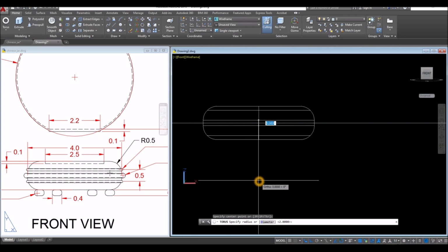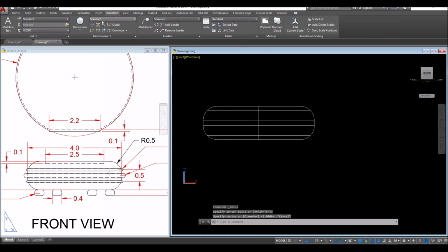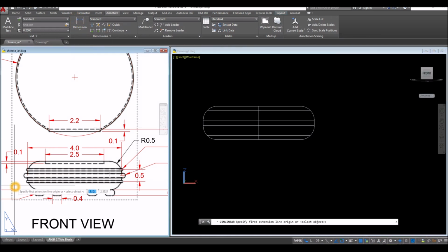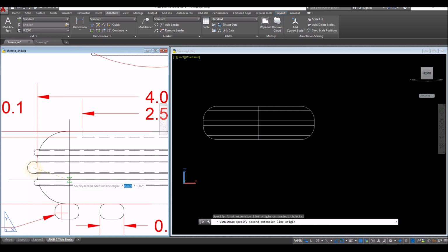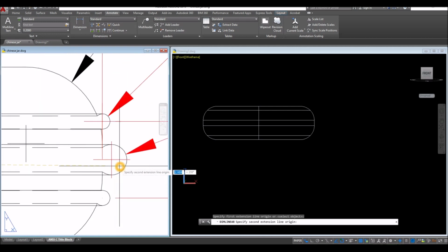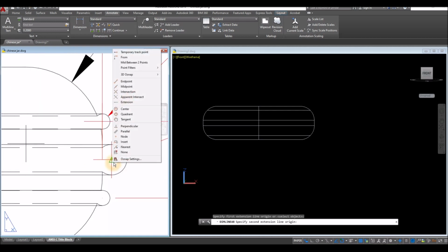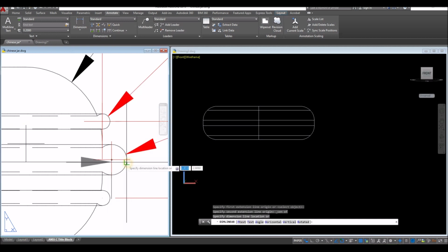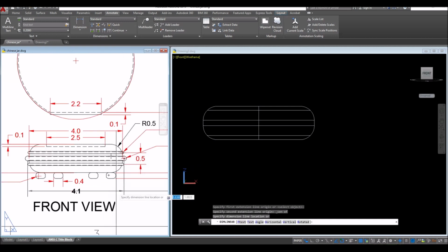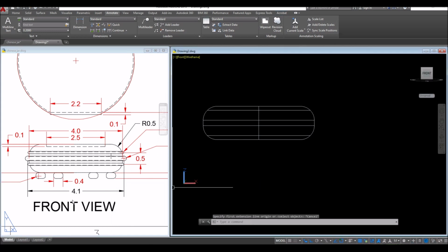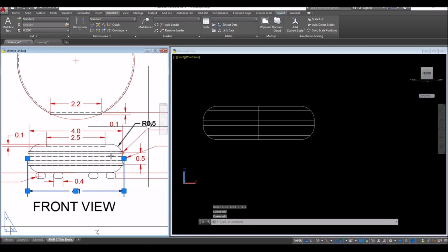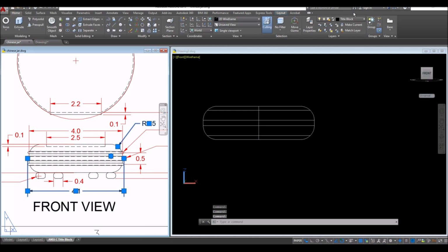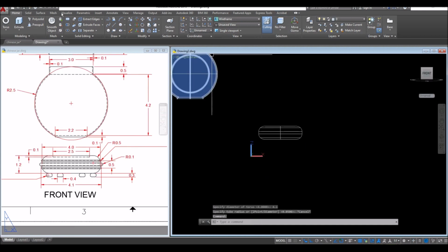diameter for that is, dimension, linear, for this window here. So from the center here to the center, shift right click and snap the center is 4.1. I should change the layer for these ones here to red layer. Alright. Torus,